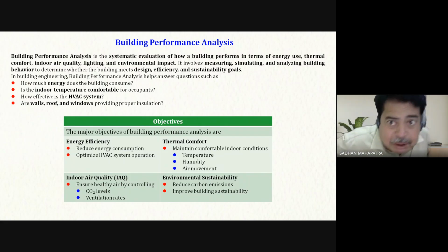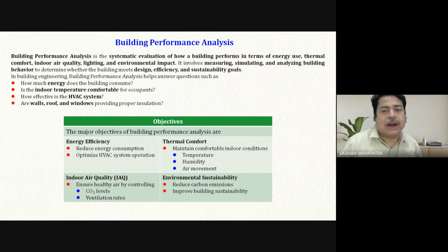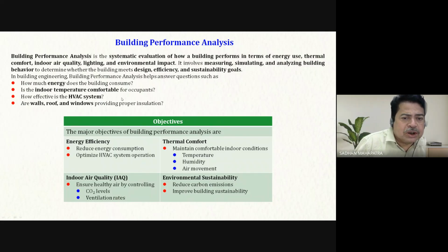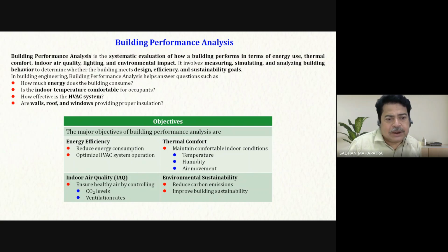So in this building performance analysis, basically we try to answer: how much energy does the building consume? Is the indoor temperature comfortable for occupants? How effective is the HVAC system? How are the walls, roofs, and windows providing proper insulation? So the major objectives are energy efficiency, thermal comfort, indoor air quality, and environmental sustainability.